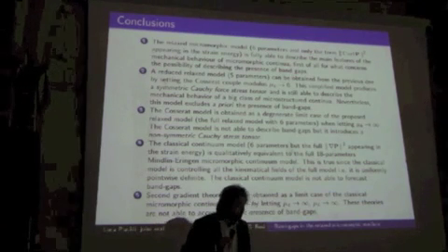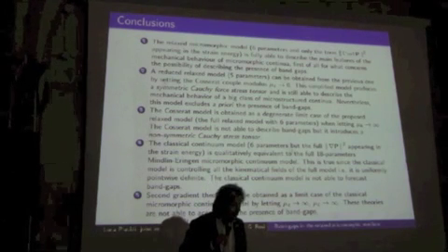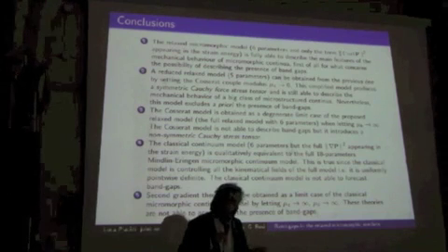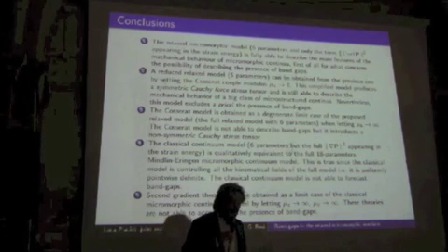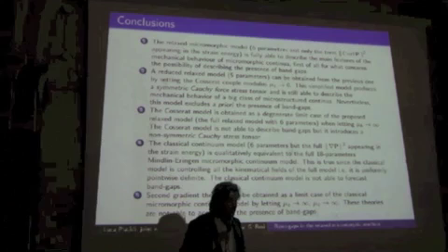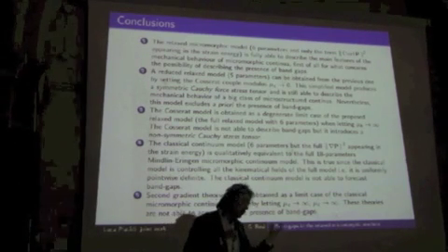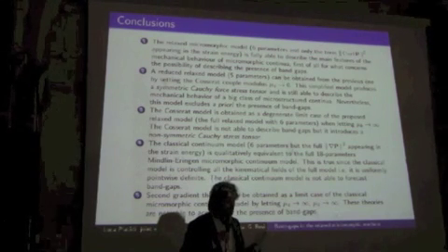The Cosserat model is obtained as a degenerate case of the proposed relaxed model, letting mu h go to infinity. The Cosserat model is not able to describe band gaps, as we have seen, but introduces a non-symmetric Cauchy stress tensor.